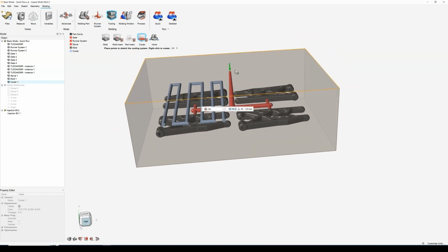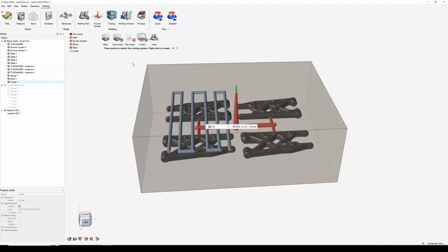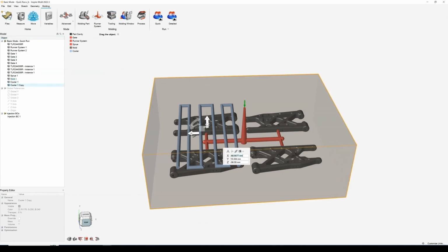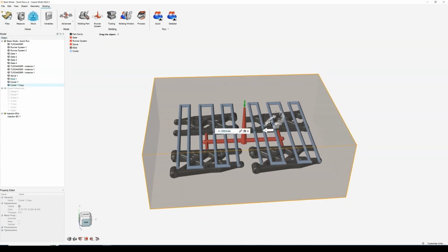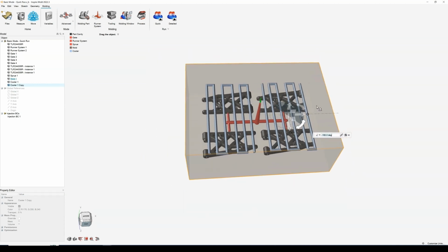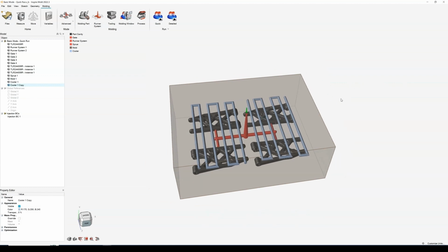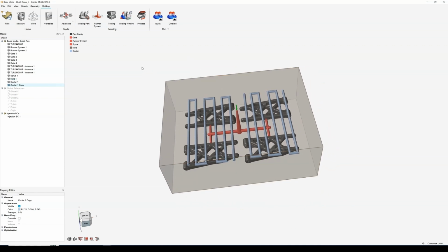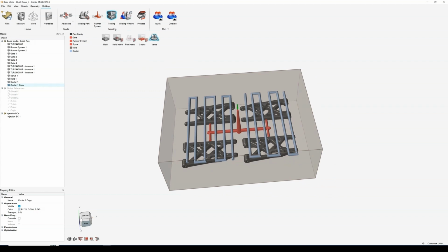I'm not going to create loads of cooling lines on this, but for example, if you wanted one on the other side, you could always potentially use your mirror tool, or you could just use your simple Windows copy and paste. So I copy, I paste, and then I could just move this one over to the right hand side. Obviously doing this very by eye, but spin it around 180 degrees, and you've got another cooling line on the other side. So yeah, you can do all sorts of things like that. Added some cooling lines now. I'm not going to do any on the underside, but you'd have your cooling lines a lot better than I've just done them there. Moving on to tooling, the last thing in tooling is venting.